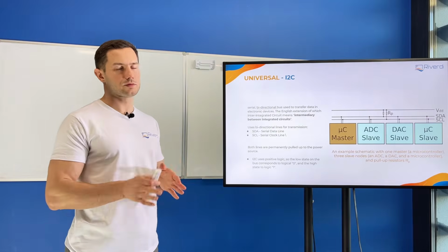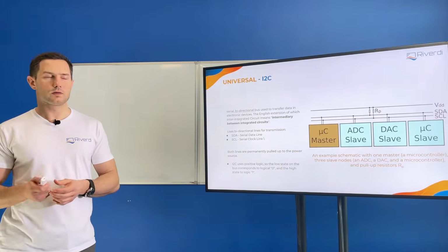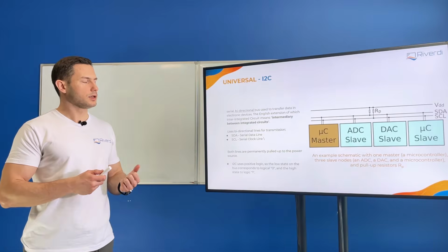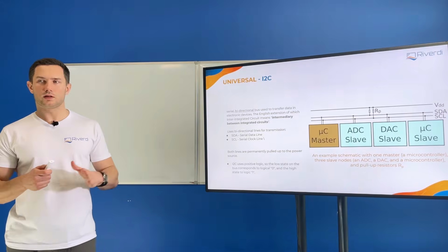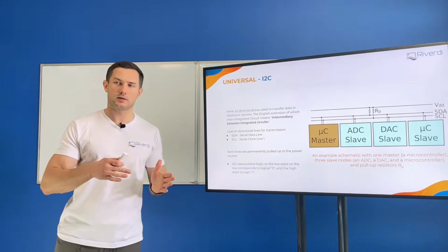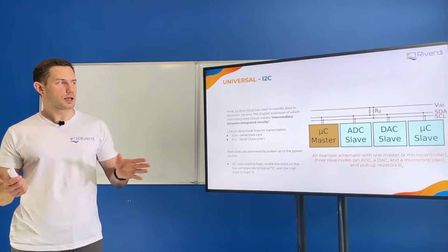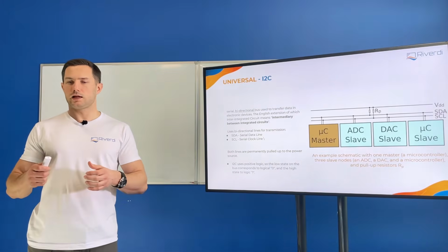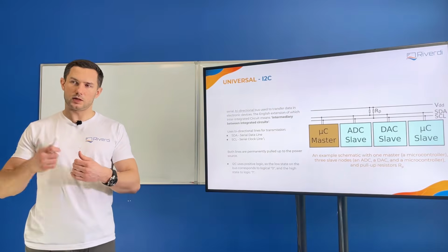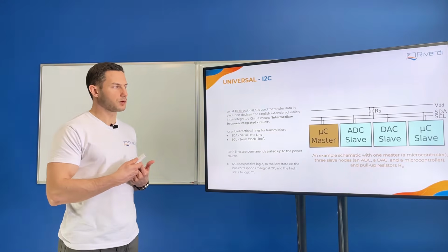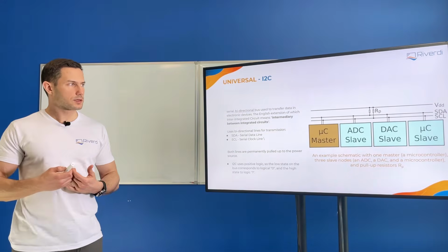So in SPI we have 2 data lines, one outgoing and one incoming, and in I2C interface we have only 1 data line. So if, for example, master is sending some data, the slaves can only receive it, and the master then needs to finish it. We need to wait a little bit, then we can respond as a slave to the master.